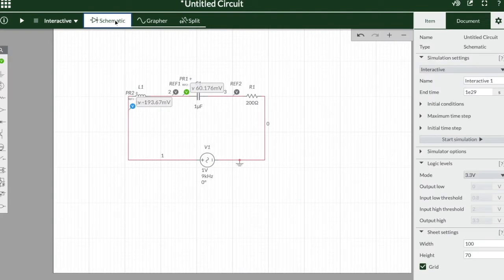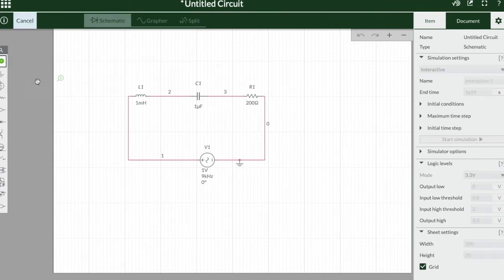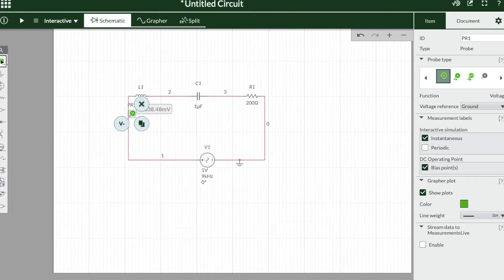Earlier, while determining the resonant frequency experimentally, we found that current in the circuit changes its magnitude along with the frequency of input signal. But does this current always remain in phase with Vs? Let us now observe waveform for current in the circuit and Vs, that is the applied voltage, and see the variation in phase difference between these two with respect to the applied frequency. While observing this, we will also observe potential difference across the series combination of inductor and capacitor.